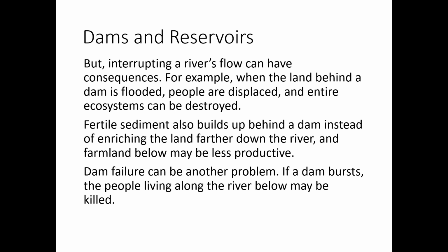And then also just by building a dam, you're slowing the speed of the river. And if you're slowing the speed of the river, that sediment that's normally floating in the water will start to drop to the bottom of the river, and even to the bottom of the reservoir, to where it can even fill up that reservoir completely.